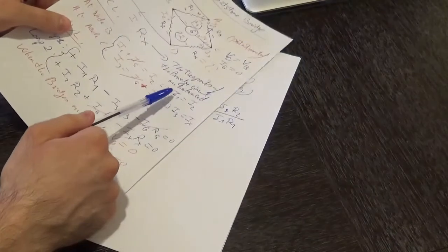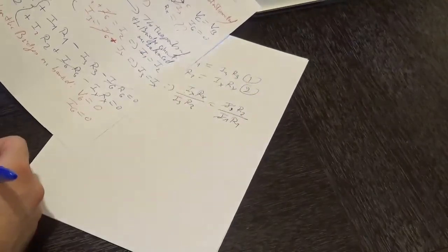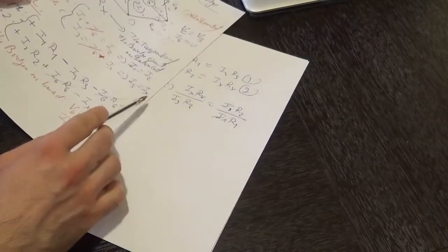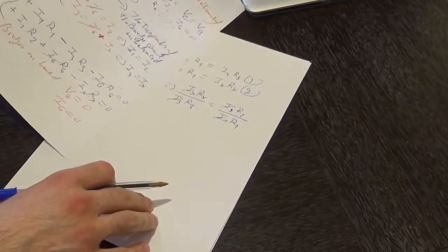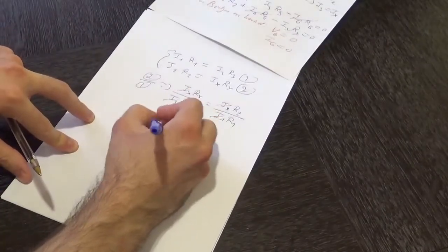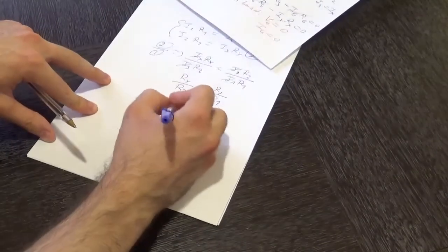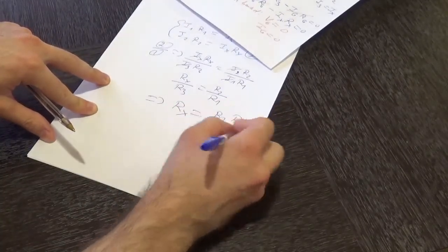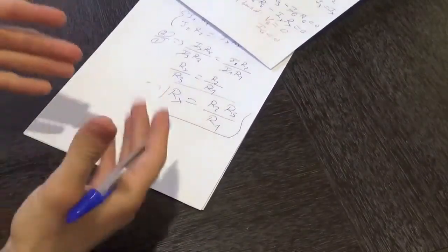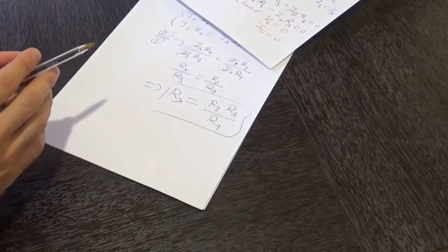Now over here we know that I1 is equal to I2. So I1 and I2 are equal, therefore we can simplify them. And over here we have I3 is equal to Ix. So I3 and Ix also cancel out, and therefore we are left with Rx over R3 equal to R2 over R1, from which we can deduce that the expression for Rx is R2 times the resistance R3 divided by R1. And that would be the final expression for Rx, which is going to enable us to determine a certain theoretical value for that unknown resistance Rx.